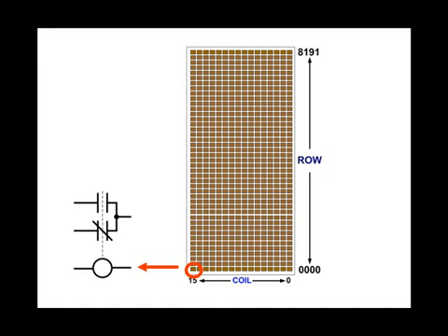The use of these contacts to check the state of the relays is the basis for all relay logic. One major disadvantage to using relays for logical control is that each contact can only be used once in a logical statement. If you need to check the state of a relay in more than one logical statement, you need to add more sets of contacts to the relay. However, keep in mind that there's a limit to how many contact blocks you can add to a relay. Each contact block has its own spring, and a relay coil only has so much force to overcome these springs, and each contact block adds more springs that have to be overcome.